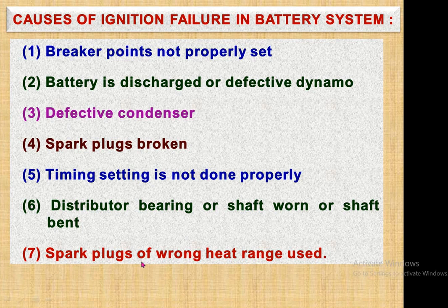battery ignition system. Spark plugs of the wrong heat range used means the proper spark plug is not used for a particular engine system. So in that case, according to the heat that has been generated during the power stroke, it is necessary to use a spark plug for a particular type of fuel. So the heat range that has been marked for the spark plug should be matched with the fuel